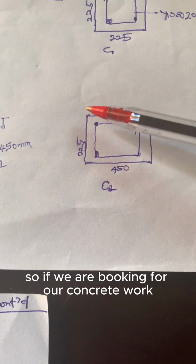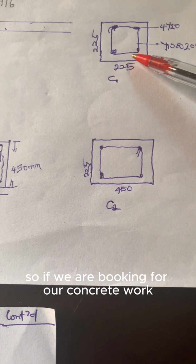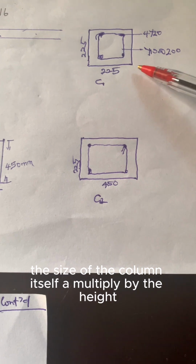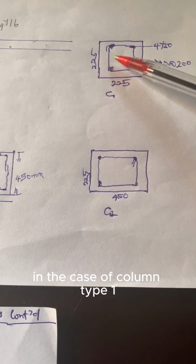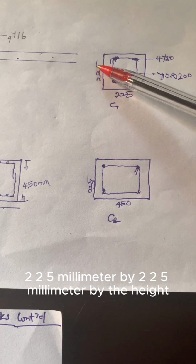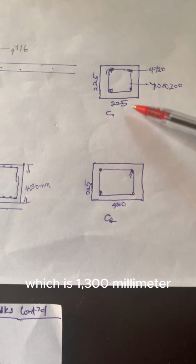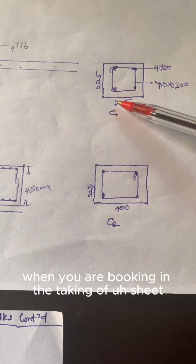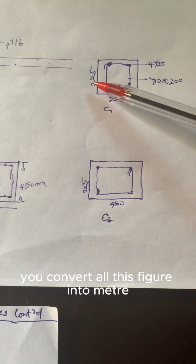millimeter. So if we are booking for our concrete work in starter column, it will be the size of the column itself multiplied by the height. In the case of column type 1, it will be 225 millimeter by 225 millimeter by the height, which is 1300 millimeter. But mind you, when you are booking in the taking off sheet, you convert all these figures into meter.